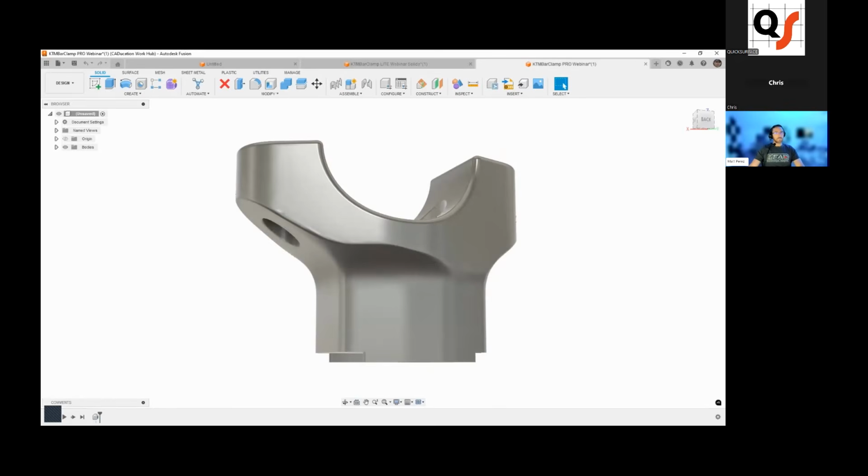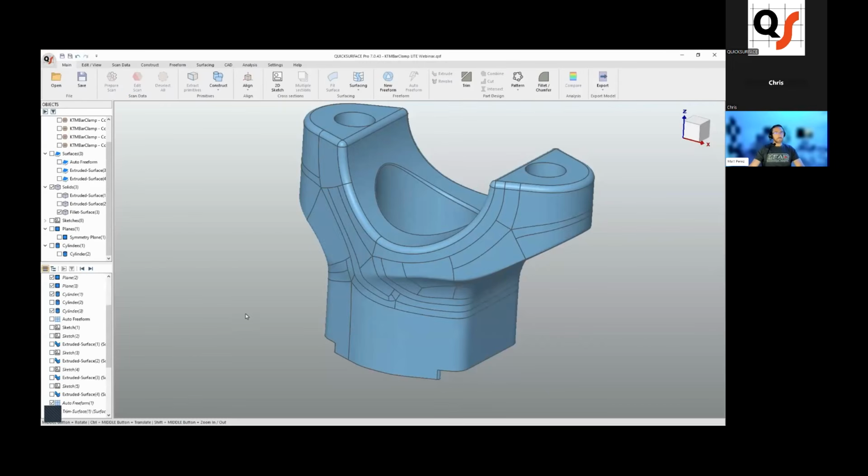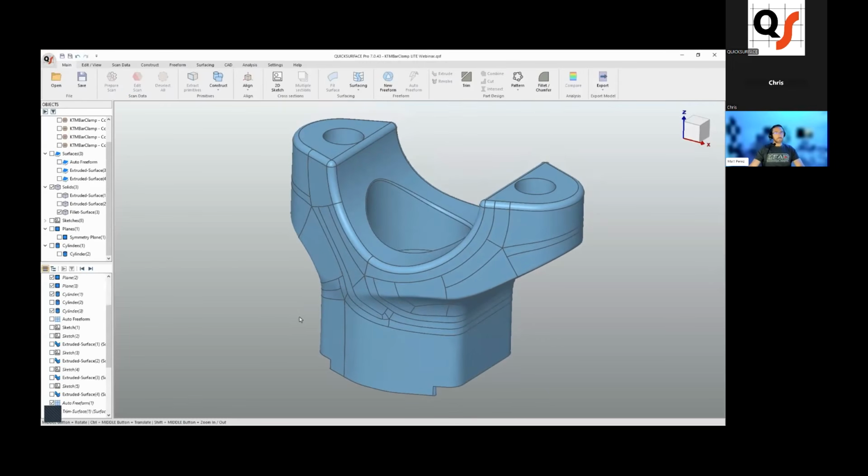And hopefully we can also see the difference in the tool set, not just the ability to create a better auto freeform, but the addition of tools like trimming with a surface, a solid or a plane to extract part of the mesh, being able to extrude and snap directly to the mesh. So if we're trying to create extrudes or features that end directly at the mesh, this is a great option. And also just the ability to do all these Boolean operations instead of having to create a bunch of individual surfaces, planes, and solids, and then export all that to an additional CAD file.